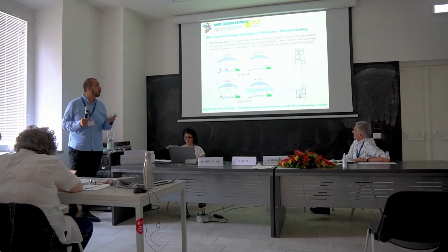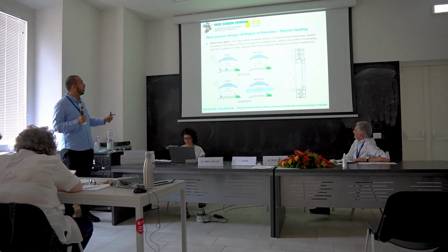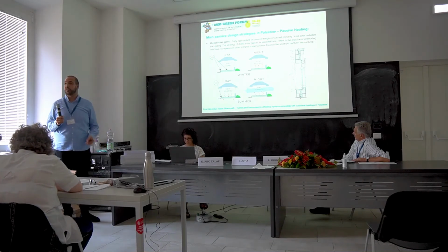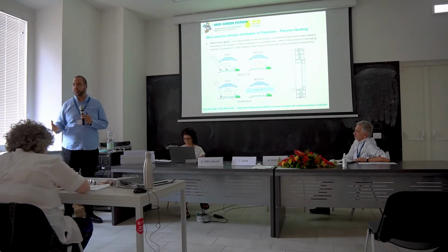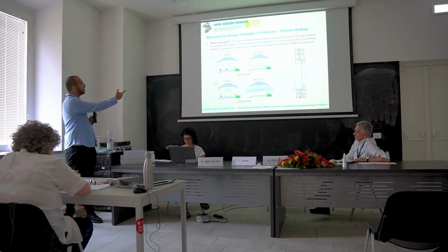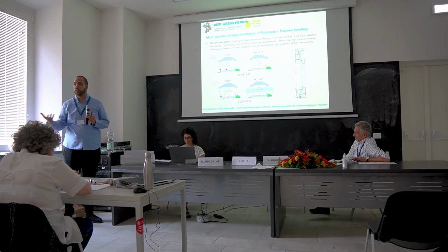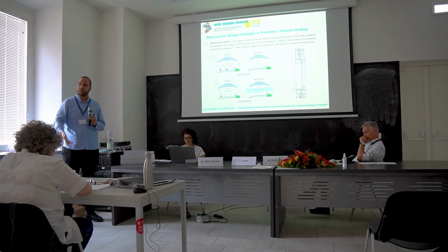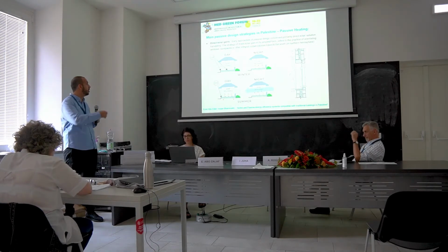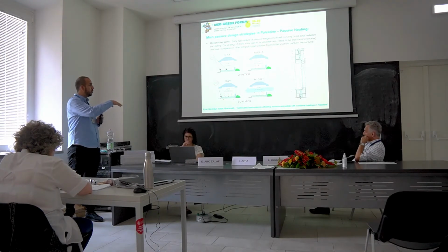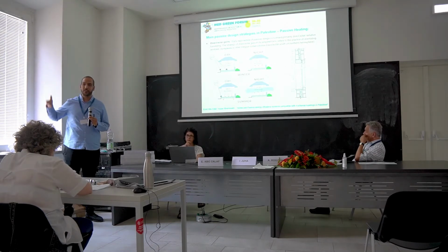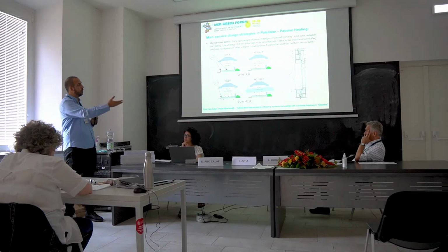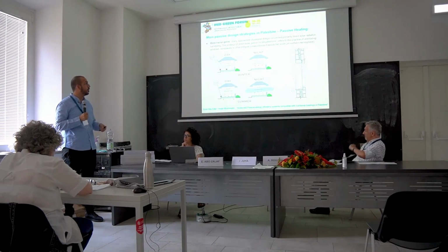Now we can talk about passive heating. We have more than one type. First, the direct solar gains. Direct solar gains use the heat from the sun's rays. In the winter, we can let it inside to heat the thermal masses, the floors and the walls, and at night it will be released to give more comfort inside the house. In summer, because of the angle of the sun, it won't enter the house, which gives more comfort. And for the heat, we can do the night flush or ventilation.